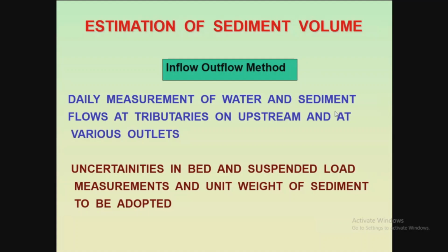Every hour or every 2 hours your measurements have to be taken, and you have to model it. So it's a tedious job, and you have to calculate that over the whole monsoon period, 4 months, and it is difficult to sit there and physically measure. Though we use the inflow outflow method in the non-monsoon period, in monsoon we cannot take it, because more sediment comes in the monsoon period only, and at that time that method doesn't support us.